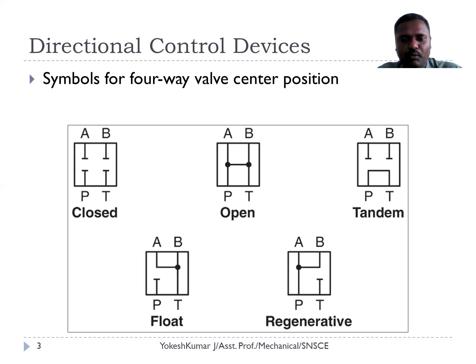And the second position, open center. Here all the ports are open. Pump port is connected to A, B and the tank port. It is used to hold the actuator at a very high force. Whenever we want to hold the actuator when a very high force is actuated, this position can be enabled.